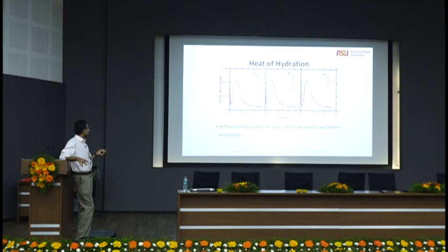You can see here, that's pure OPC. And then if I take 0.7 micron limestone, really, really fine limestone, with a cement particle median size of about 15 to 20 microns, and replace 10% of the cement with this limestone, which is not reacting, but look at the hydration heat.